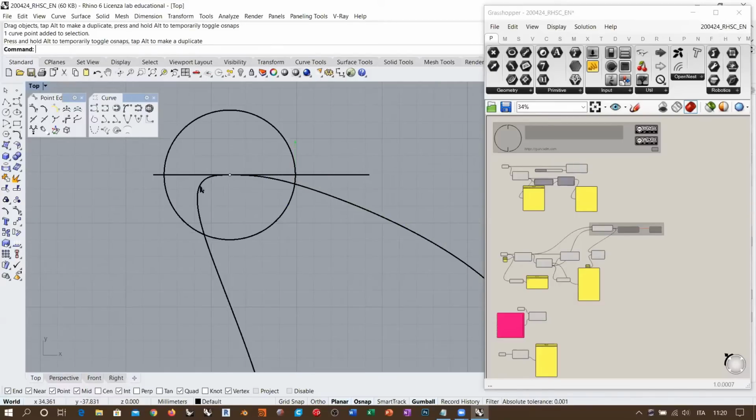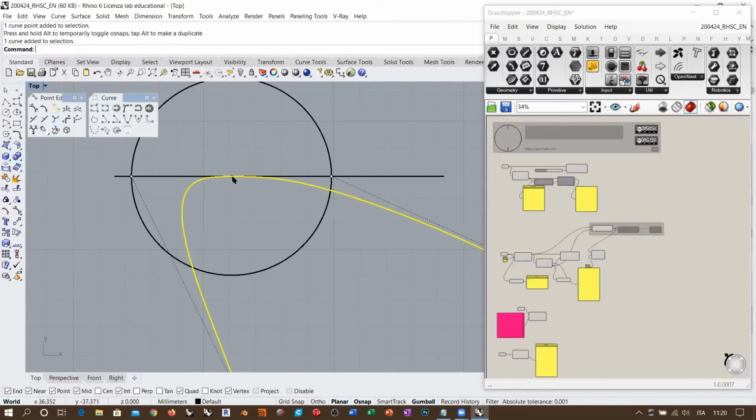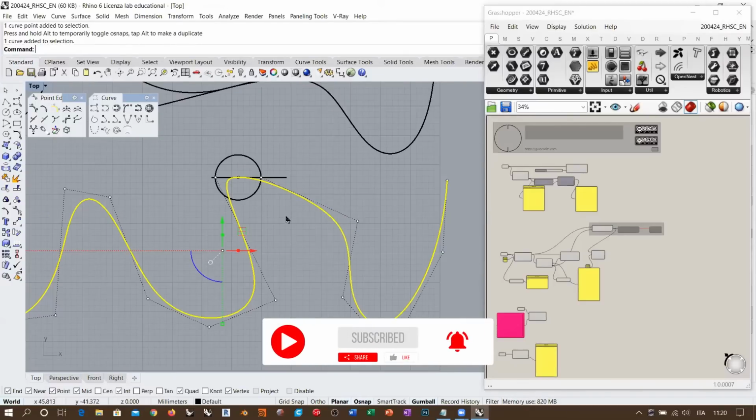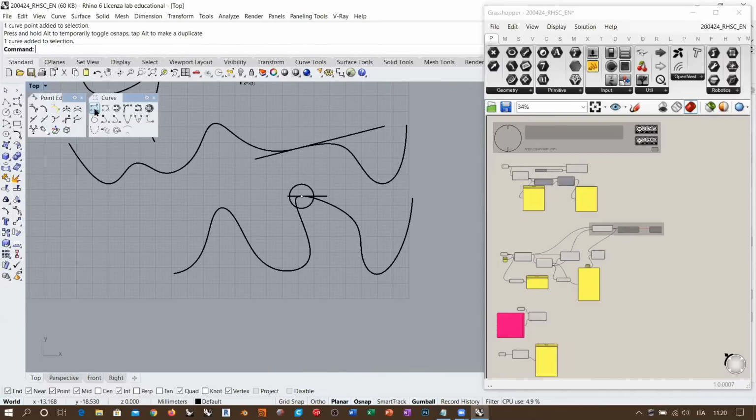So actually, if I want this curve to pass through a specific point, what I need to build is this kind of situation: 3 control points in a row with a constant separation between them. And in that case, the curve will pass through the mid control point. And this is actually what is happening here, okay? So I know that if I want to work with NURBS control points, I can force the curve to pass through a specific point by aligning 3 control points and keeping a constant separation between them, okay?